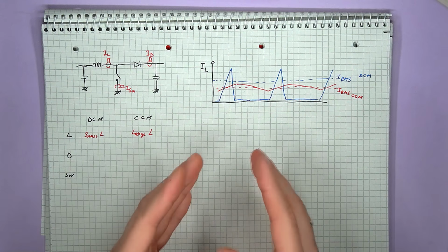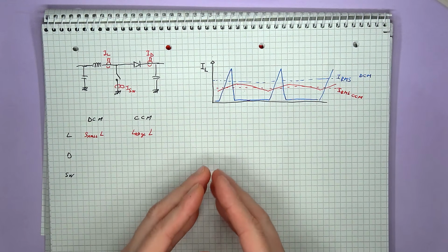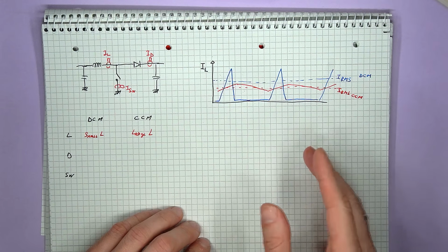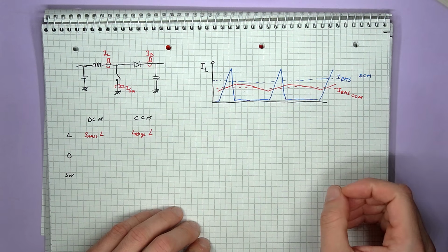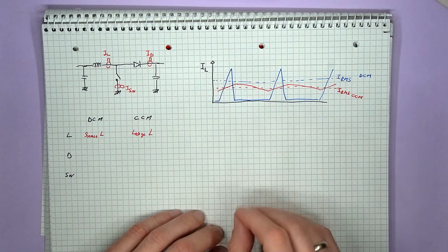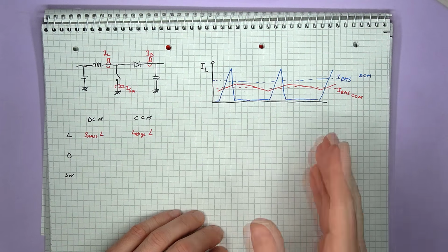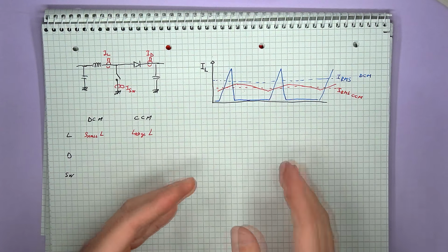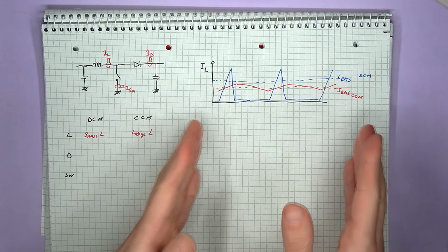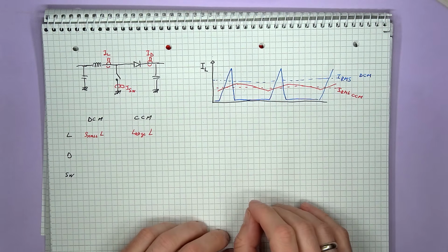If we plot out the typical inductor current for the two modes of conduction, we will observe that the RMS and peak current for discontinuous conduction mode will be larger. Now, from an efficiency point of view, this is not really a problem, since a smaller inductor in the same package will usually have a smaller on resistance, so this particular topic should not affect efficiency.